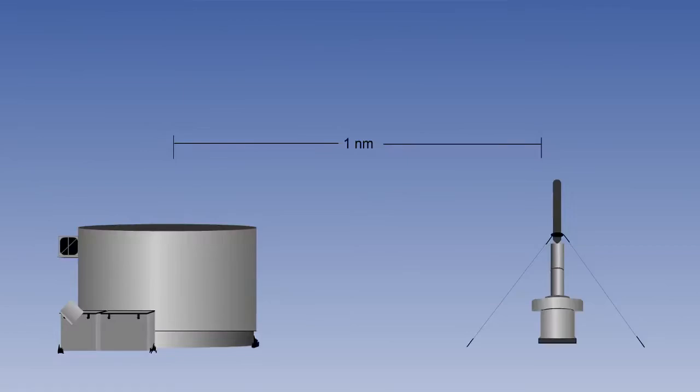If the VOR and DME equipment are at entirely different locations, which is deemed to be more than 6 nautical miles apart, then the equipment is not paired, and the idents are different.